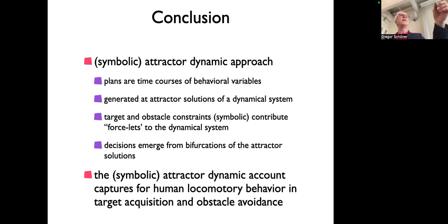And so, for instance, here on the A40, this so-called Schnellweg, even though it's not very fast, often there's a lot of traffic jams, and they had it instrumentalized. I think the measurement devices are still there, but no longer functional. So on every bridge and any of these signs, they had measurement devices, and they would be able to construct the flow from that, and then were able to show that these shockwave dynamics really apply. The shockwave dynamics essentially, when there is a slowdown point, then the density increases, because when density increases, the average throughput decreases, the capacity of the road decreases, and that amplifies that effect. So it's the self-amplification of the effect.